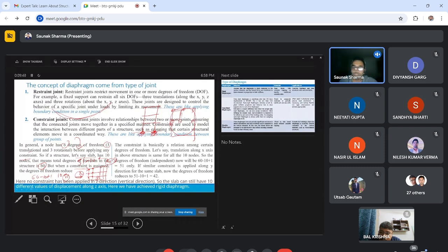So the slab or diaphragm is not so effective that it acts as rigid and does not deflect in its out-of-plane action, but in in-plane action it is so rigid that we can consider it rigid and it deforms by the same value as a whole, because its stiffness is b d cube by 12, and this depth is much higher, so it acts as rigid.